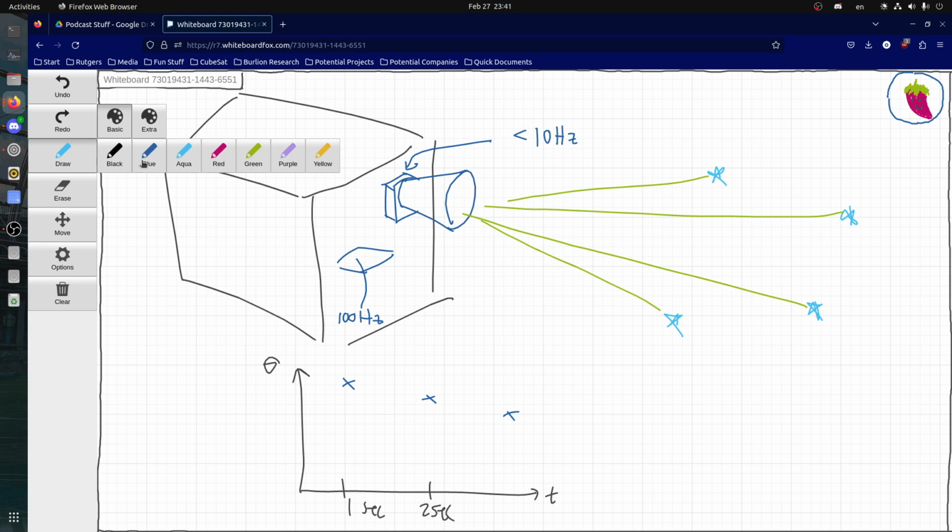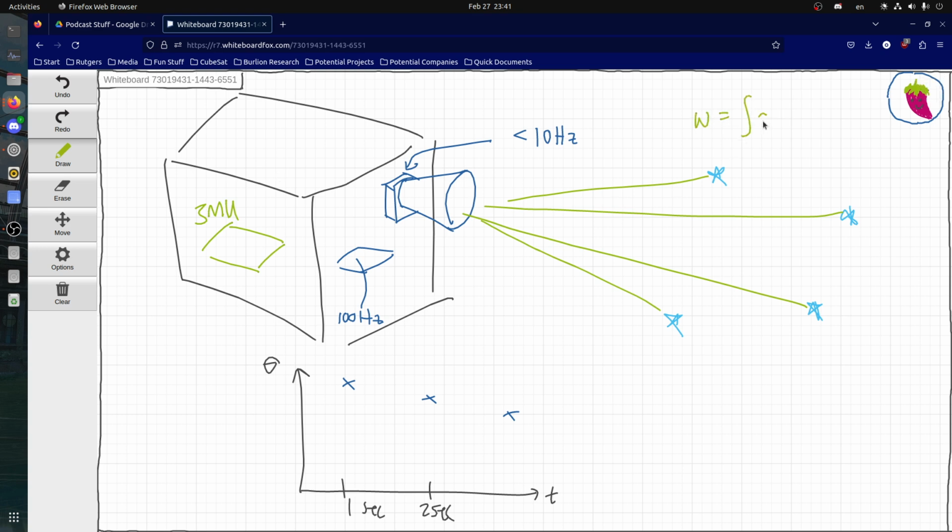So what we do is we have an IMU, an inertial measurement unit, which all it does is give you the angular acceleration and, I guess, the linear acceleration as well, right? And then using the integrals, the lovely relationship of w is equal to the integral of a(t) dt from t0 to t1, and then integrating again for position. So theta is equal to the integral from t0 to t1 of w(t) dt. This isn't a raw sense. This is mathematically what's happening.